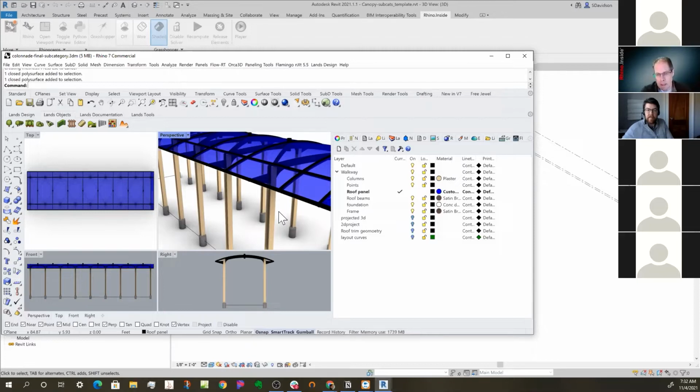One of the things, and we may discuss this by the end, is that there's a lot of ways you can stuff information in a Revit model or in a Rhino model, and you're going to find that Rhino.Inside.Revit demands and pushes you to try to find ways to put more and more information in the Rhino model so that you can organize it properly in Revit. So in this case, I'm just using layers. So I have these layers here, and these layers are reflective of the category that I want to use in Revit.